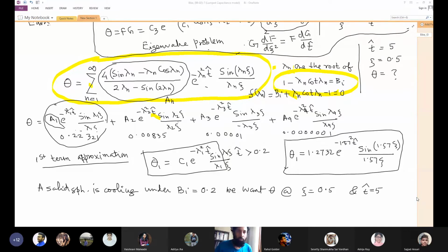All right. So everyone got this, able to read those? It's a reading table, but in the exam you have to read this table, so just be sure that you can read it well. Anyone has any difficulty? How to decide whether to approximate the value of theta by seeing the value of t hat? T hat greater than 0.2, happily you can use the approximate solution. The first approximate solution means this is the first term of the series. So t hat greater than 0.2.